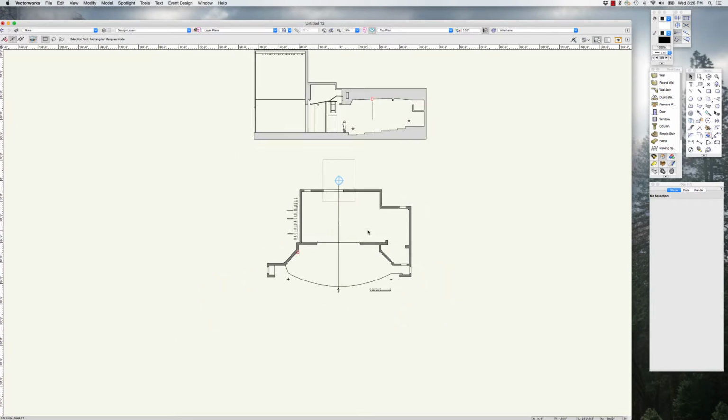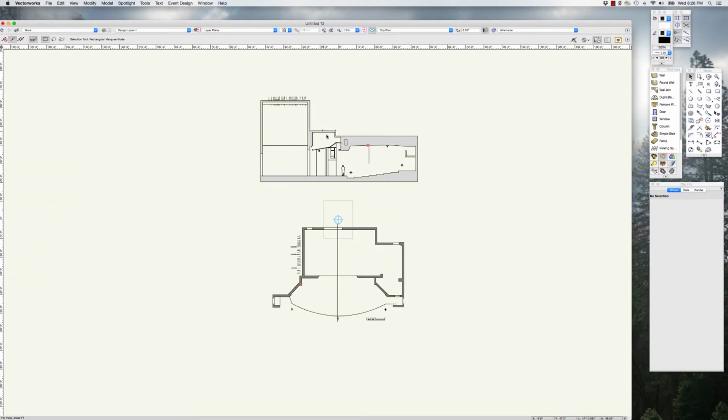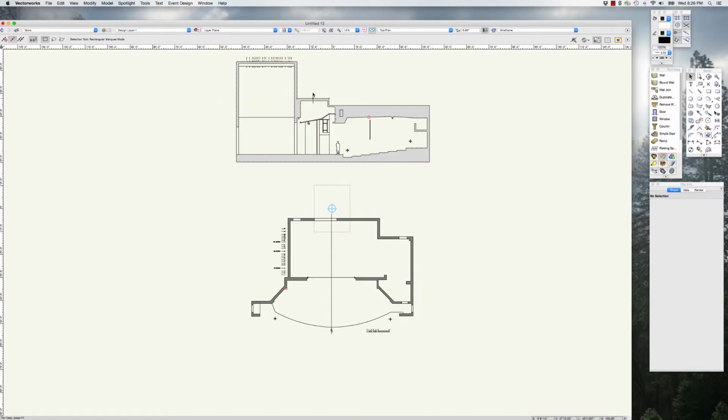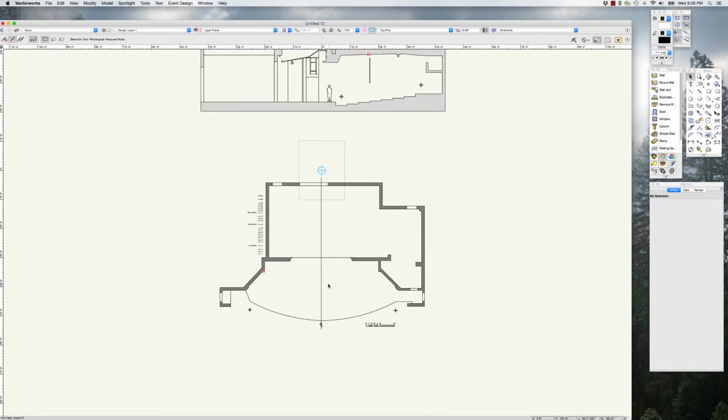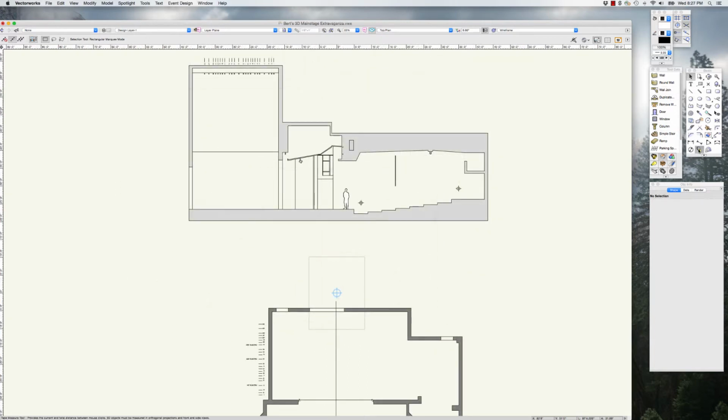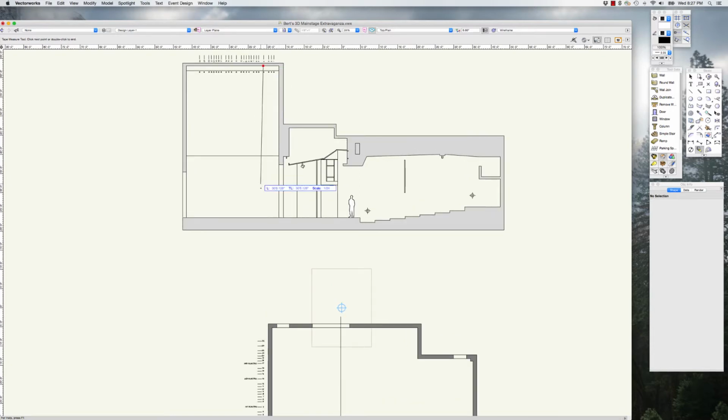I point that out because when you look at the section, you'll notice the walls are all different heights. The fly loft is of course taller than the auditorium is. We're just going to build our 3D model with all the walls the same height because it's faster. If you're really interested in how to make this more accurate, I'll be happy to talk to you individually, but I've never had a problem just doing it like this. So I'm going to take the tape measure here and decide that I think I'm just going to make the whole space as tall as the fly loft is, approximately.